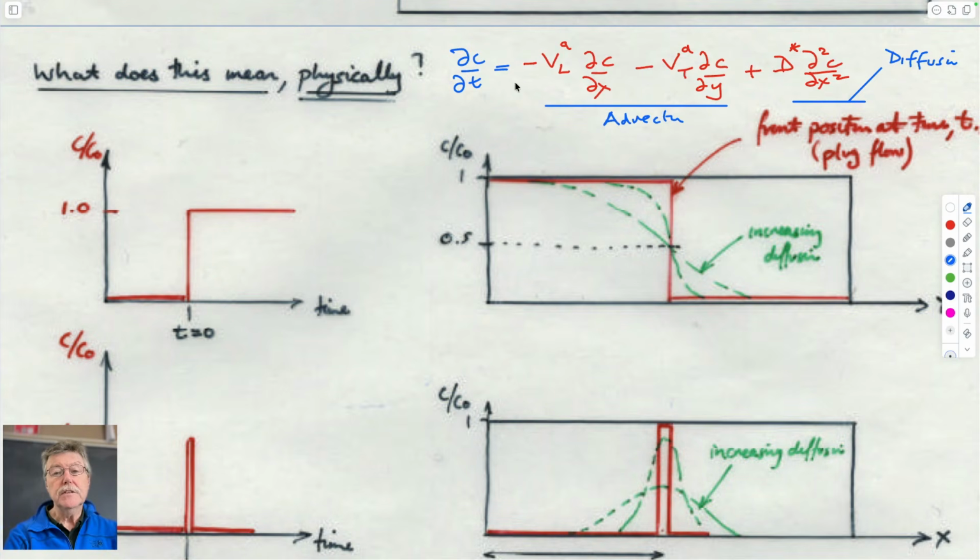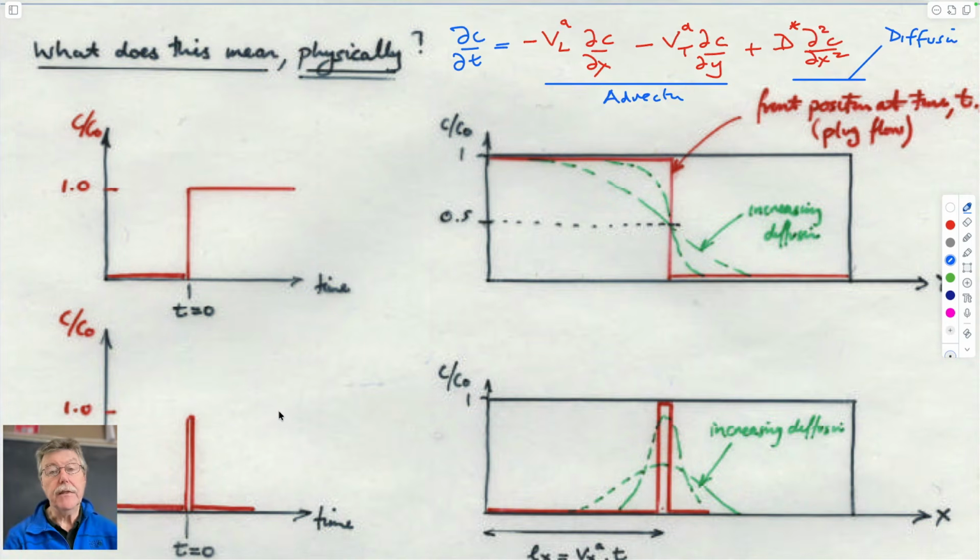This represents the dissolved mass that's carried in by the water flowing in one side of the beaker and flowing out of the other side of the beaker, if we look at it ensemble. This is the amount that diffuses in by Fickian diffusion, and the difference between how much goes in by both of these mechanisms and comes out is the accumulation, this term here. And so that's all we need to really understand about that. So now what we can do is see what each of these portions mean.